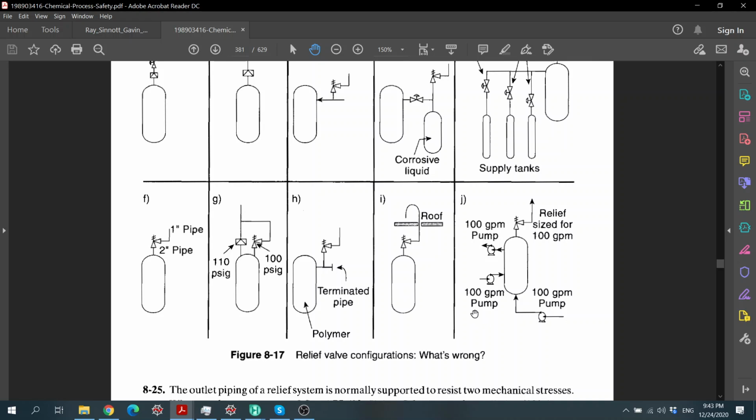So we have to know what the set point is, the maximum pressure it can handle, which is the set pressure, and then the pressure downstream, because the amount that you can release depends on the pressure here and the pressure there. The difference between them is the amount that we can release instantaneously.